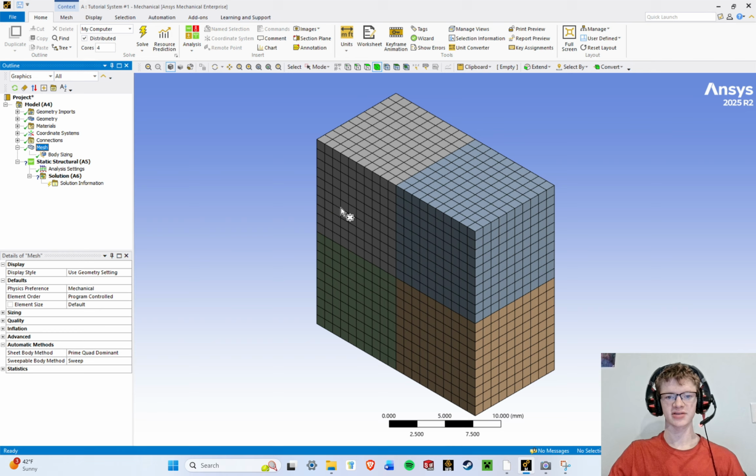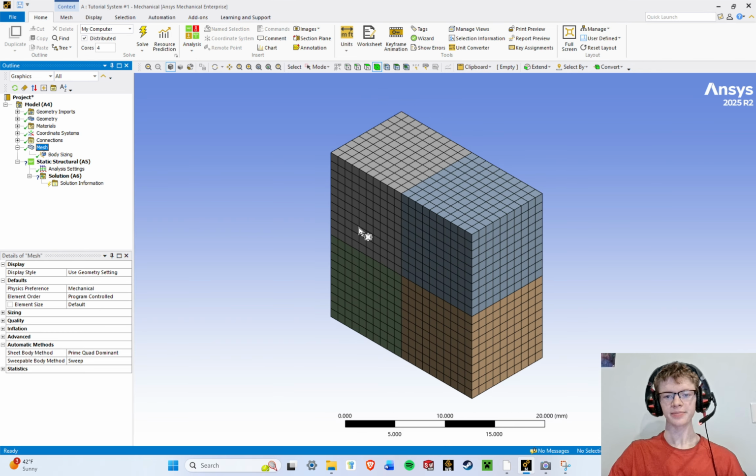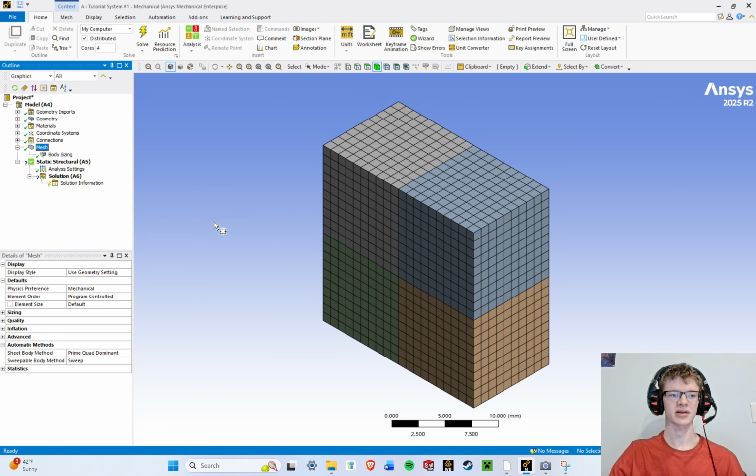So, like I said, solve it with a coarse mesh, and then make sure everything makes sense. Then go to a finer mesh, make sure the mesh is good, and then solve the rest so that you can get very precise results once you make sure that everything is set up correctly. So that's all for mesh, and you can close that, and we'll move on to the rest.